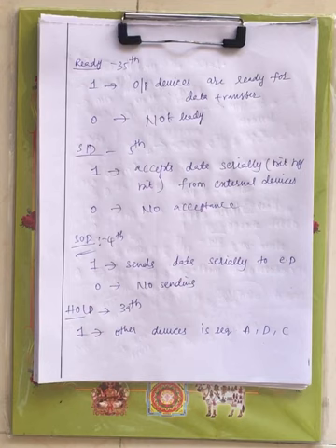Now ready is used by the microprocessor in order to sense whether the output devices are ready for the data transfer or not. When it is 1, output devices are ready for the data transfer. When it is 0, they are not ready.